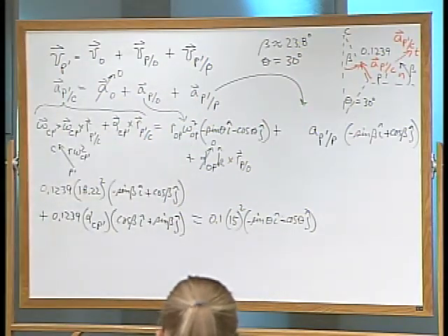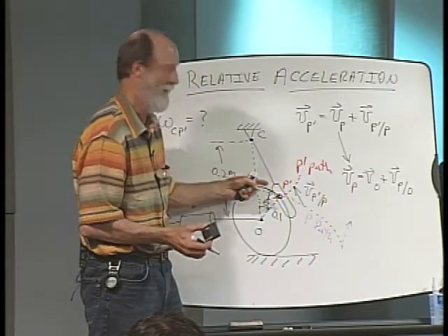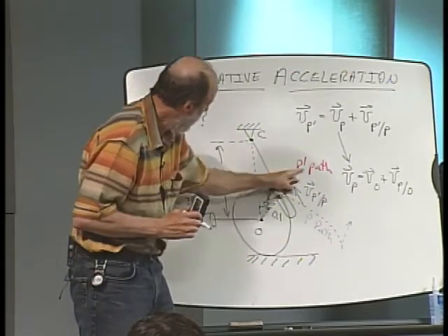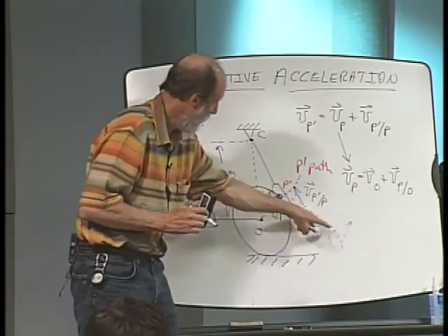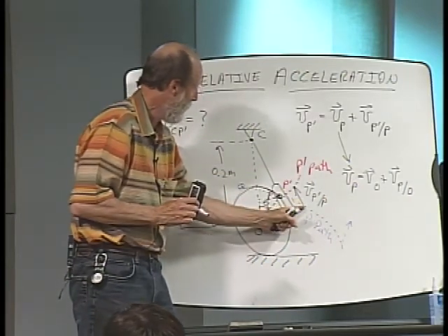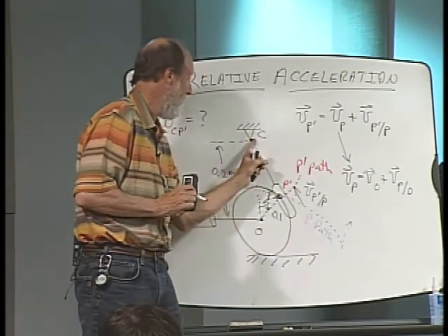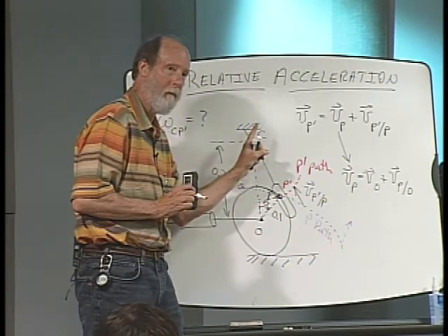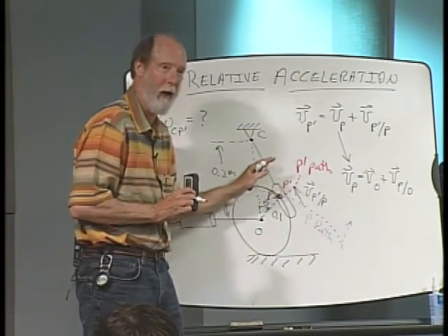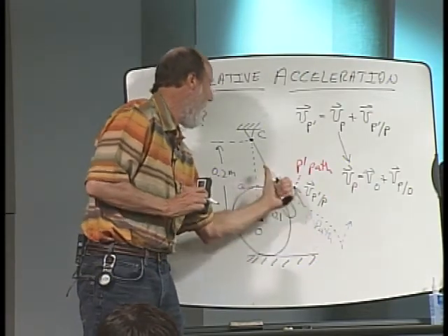Come back over here for a second. Okay, so notice our two arcs. When we did these two arcs, here's our cycloidal path, here's the path of P prime, circular. And the relative velocity of P prime relative to P is that way, back towards C, only. There's no tangential component on velocity. That's the direction of its speed. Its relative acceleration is exactly that direction as well.